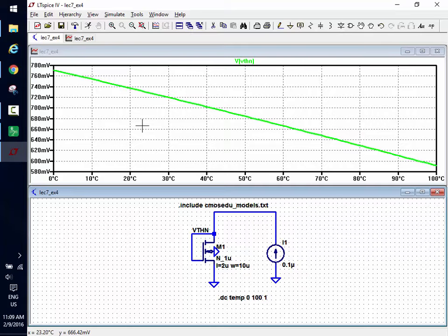What happens to the leakage through the transistor as temperature increases? Yeah, it goes up. The battery drains. So this is a huge problem nowadays in your electronics, because the threshold voltage dropping allows more leakage to occur with temperature going up. Any questions?